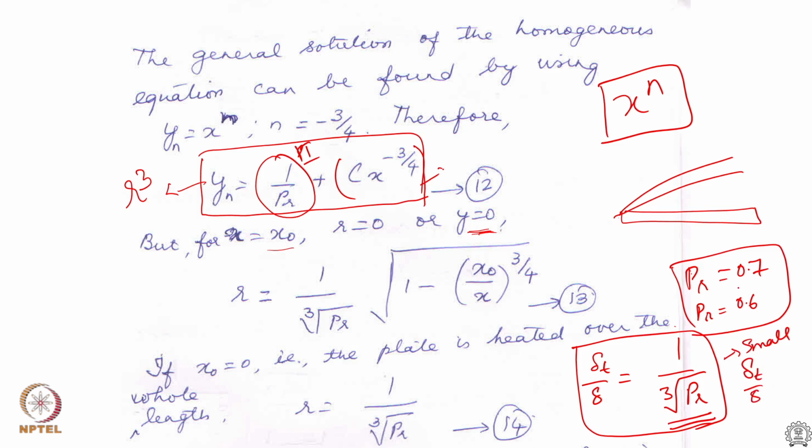However, this assumption is invalid if we are talking about Prandtl numbers which are much less than 1, in the case of metals, molten metals. For Prandtl number greater than 1, which is like viscous oils, this expression holds true and there is no issue, and we can use it as accurately as we want.